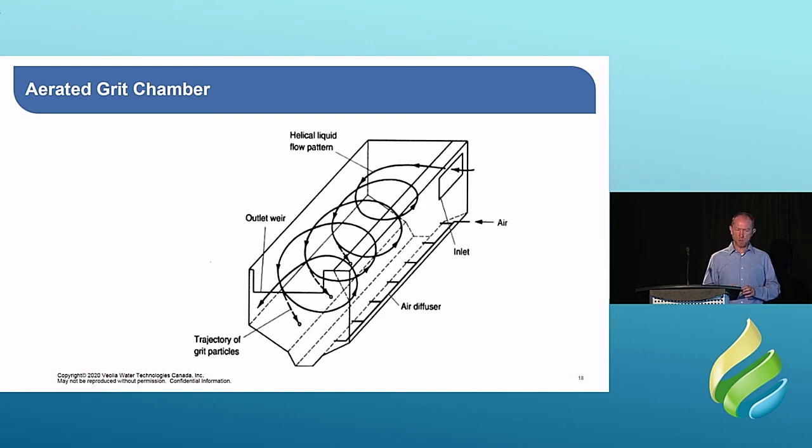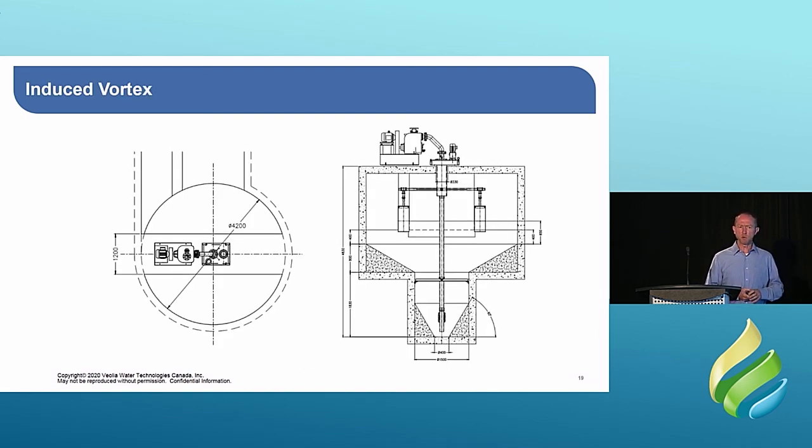So aerated grit chambers are certainly quite a common technology around. It was the standard for many years. But these days things have moved on a little bit, and really these days new systems, new wastewater plant upgrades are going to involve some kind of vortex grit removal process.